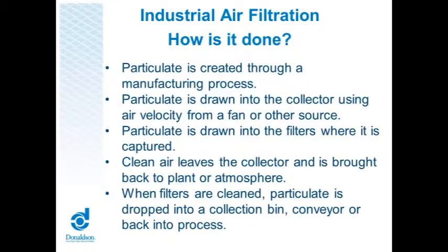Dirty air typically stays on the outside of a filter. The clean air passes through and then is discharged out the fan discharge. So if you're in a climate like I'm in, in Minneapolis, we like to keep our BTUs inside and not have to reheat that air or recool that air. So a lot of times people will recirculate air back into the building. If you've got a toxic material that you don't want to dump back into the atmosphere, it depends on what you're doing there.